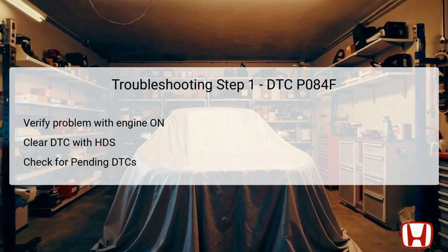After performing these actions, the next step is to check for any pending or confirmed DTCs, again using the HDS. If P084F is indicated, it confirms the issue is persistent and you should proceed to the next troubleshooting step. If the code does not appear, it may point to an intermittent failure, warranting checks for loose connections or terminal integrity at the TCM.